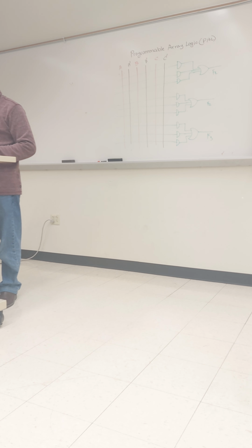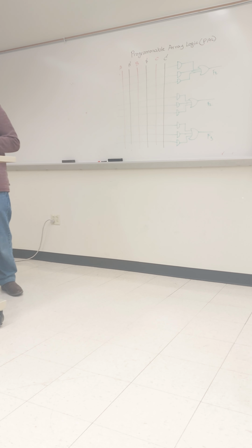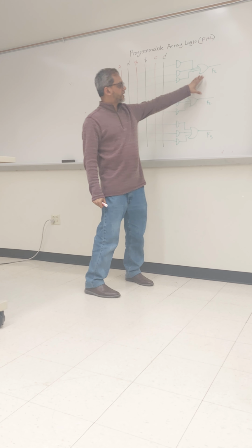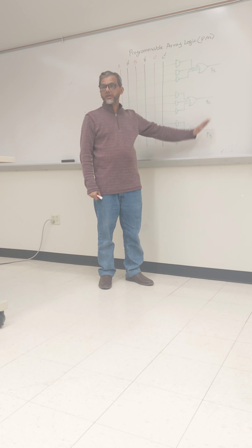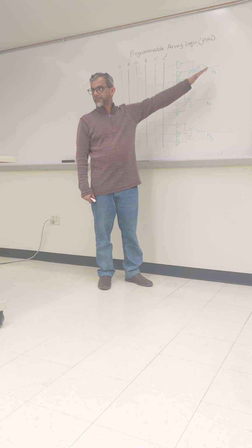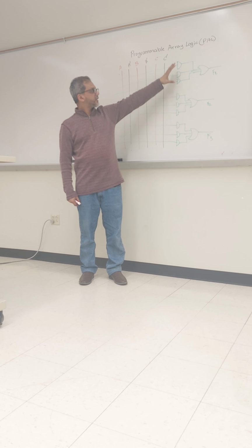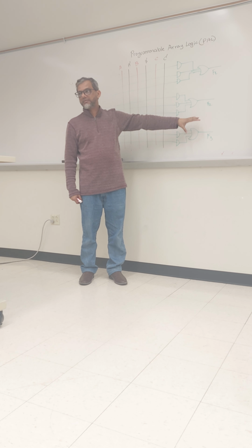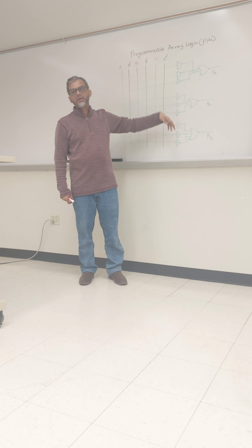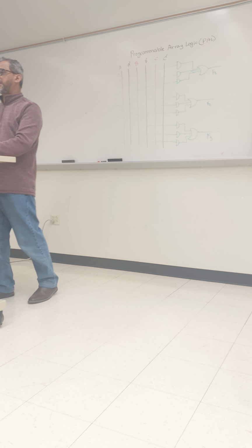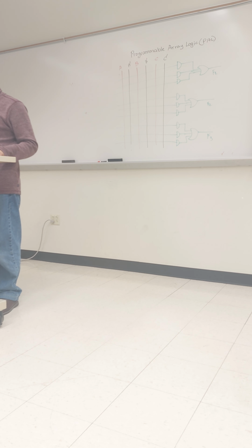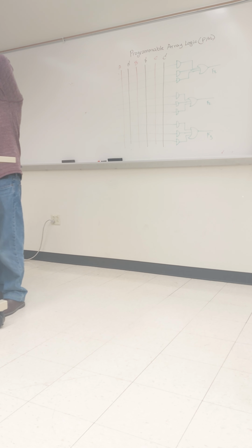So this is the very general configuration. Each OR gate will represent an individual function. So here we can say we have 3 functions. And here, just for simplicity, I maintain all the 3 OR gates with the same number of AND gates, but it can be changed. But typically 3 to 4 minterms, that means each OR gate will have 3 to 4 AND gates. Okay.